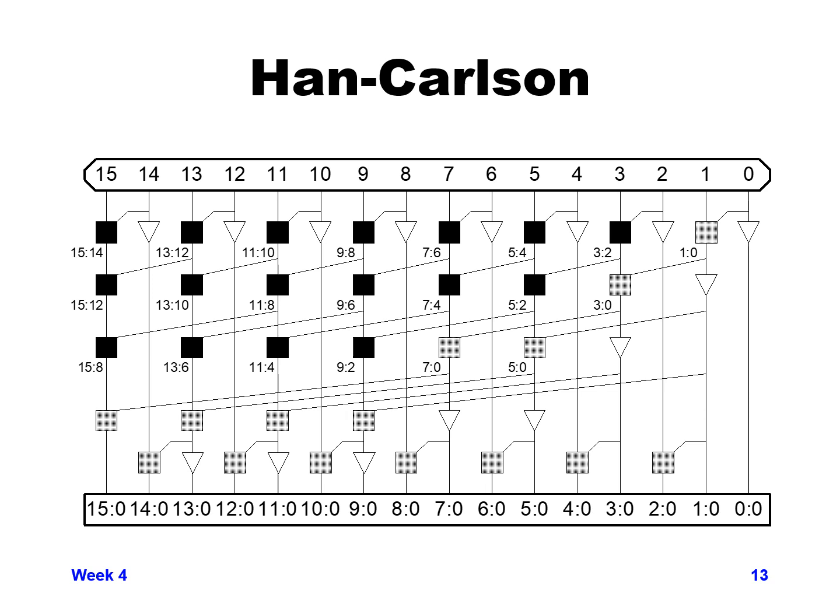So you can see this doesn't have the total minimum number of logic levels, but it does have less logic levels than the maximum amount for the tree adder. But it does have more wire tracks in it, but it doesn't have the maximum number of wire tracks that the previous design that we looked at had. So it's balancing between the Kogge-Stone and the Brent-Kung design in terms of logic levels versus wire tracks.